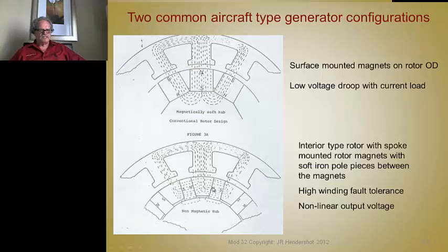But in this case, you use rare earth magnets, and under normal operation, the flux linkage takes this path here. But if you get a short in the windings, you'll get a very high short circuit current in the winding, so the MMF in the stator is very high, and so the flux will not take this path. It will go this way.